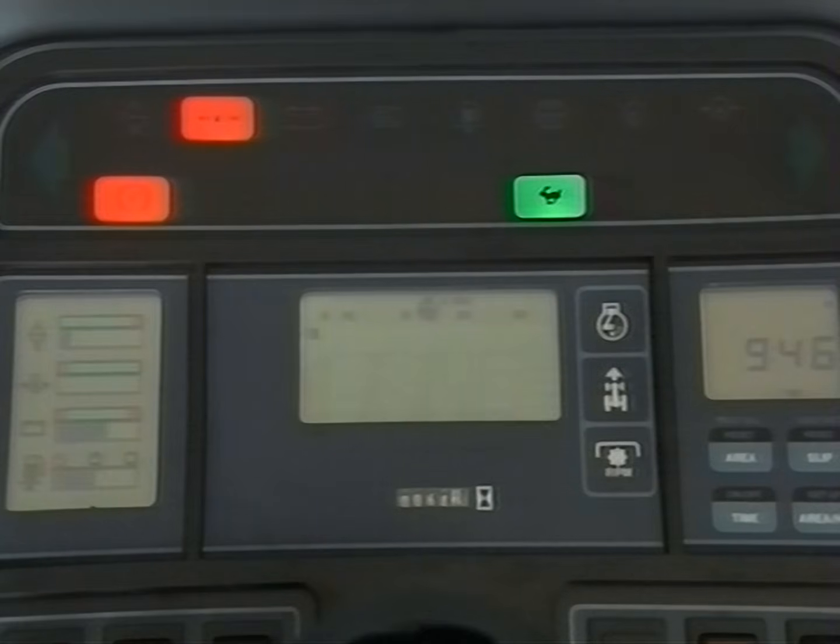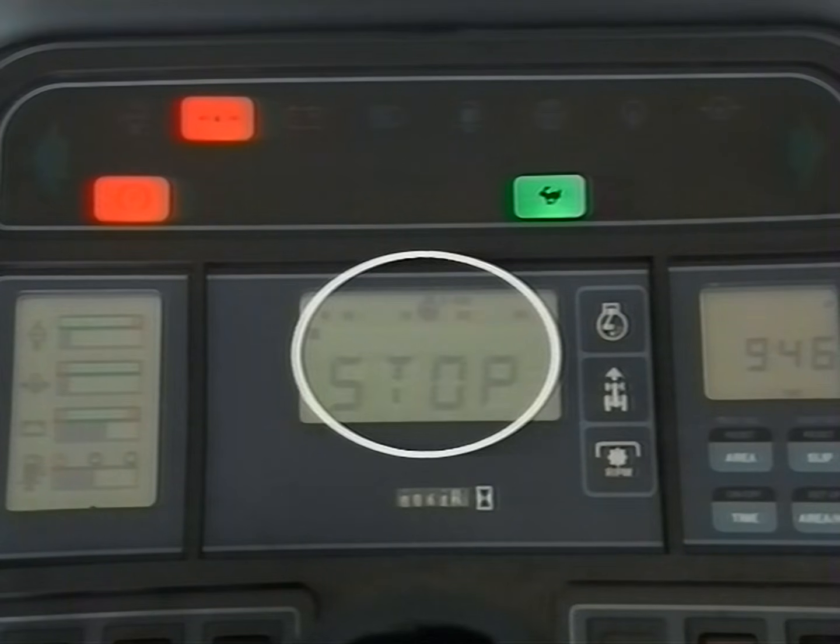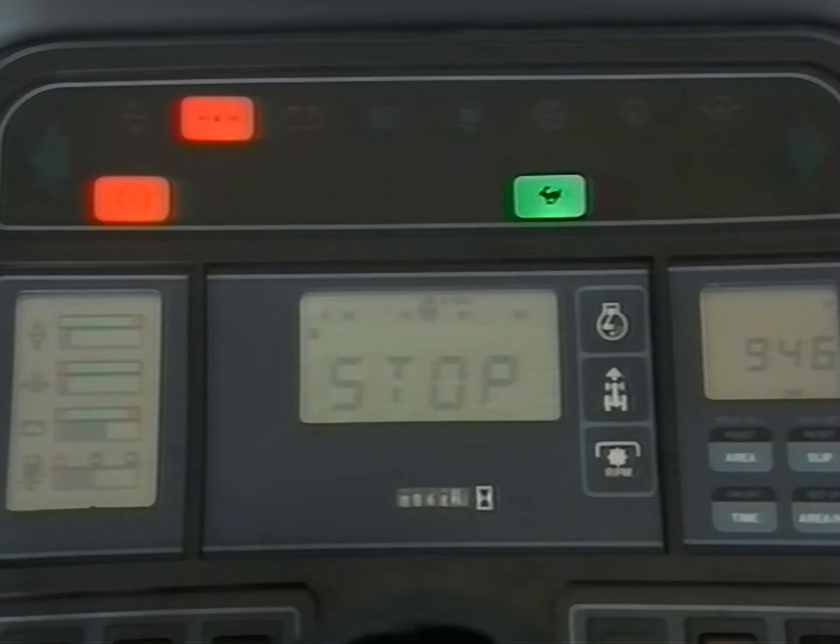When the electronic instrument panel senses that a system is not within normal operating limits, it uses a variety of warnings to indicate this to the operator. Let's look at one of these conditions: low engine oil pressure for a given RPM. When a tractor engine is running and engine oil pressure is too low for the engine RPM, the low engine oil pressure warning lamp lights. One segment of the oil pressure bar graph flashes slowly. A stop message flashes slowly on the digital display, and a continuous alarm sounds.